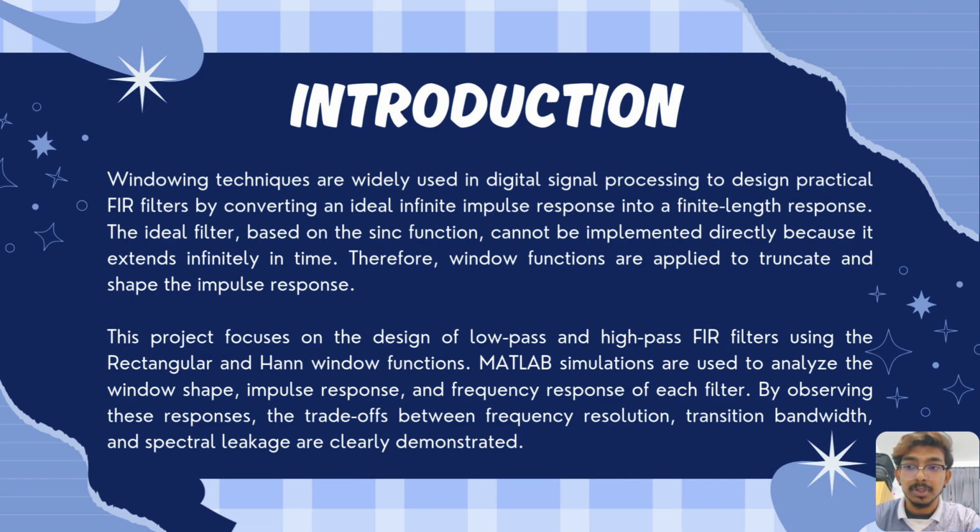Moreover, in this project, we just focus on the design of low pass and high pass FIR filters using the rectangular and Hann window functions. We also use MATLAB for our simulation. In that MATLAB simulation, we analyze the window shape, impulse response, and the frequency response of each filter. By observing these responses, the trade-off between frequency resolution, transition bandwidth, and spectral leakage is clearly demonstrated.